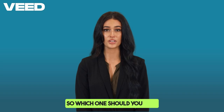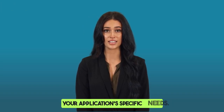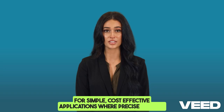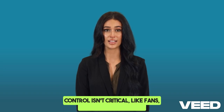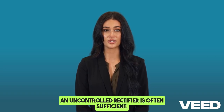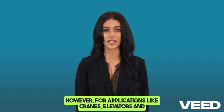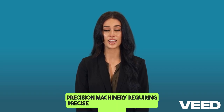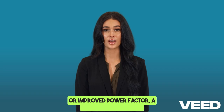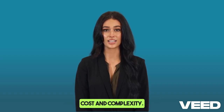So, which one should you use? It depends entirely on your application's specific needs. For simple, cost-effective applications where precise voltage control isn't critical, like fans, pumps, and conveyors, an uncontrolled rectifier is often sufficient. However, for applications like cranes, elevators, and precision machinery requiring precise control, regenerative braking, or improved power factor, a controlled rectifier is the better choice despite the higher cost and complexity.